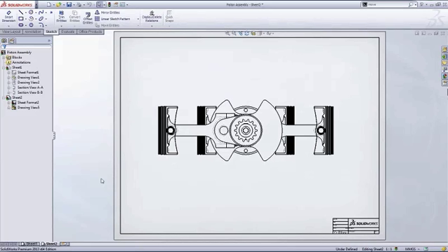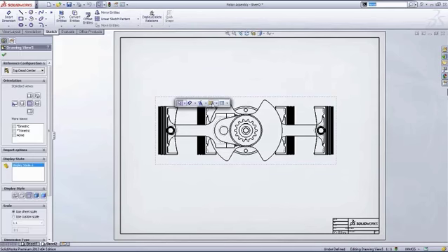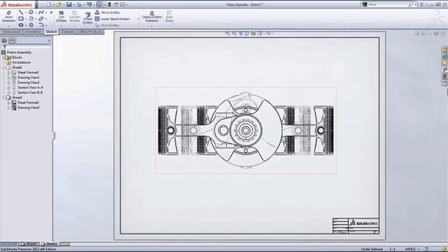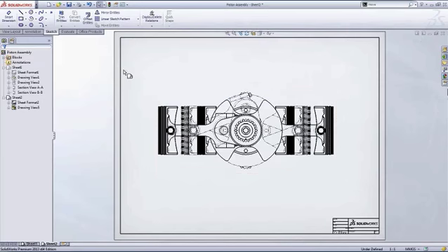way. But what if I wanted to show those two different positions, top dead center and 90 degrees, I just mentioned? This is where alternate position views come in, and is definitely another favorite of mine. When you choose to create an alternate position view, SOLIDWORKS will give you the choice to either create a new configuration on the fly or use one that already exists in the assembly, for instance the 90-degree configuration I just mentioned. SOLIDWORKS then creates sort of a silhouette of the 90-degree configuration over the top of our existing view.